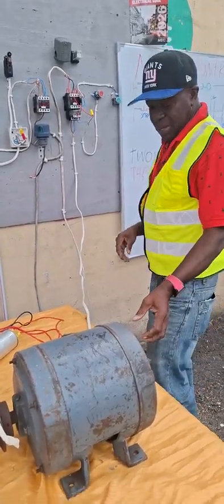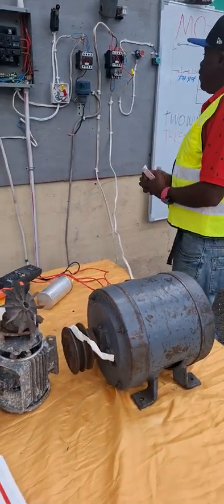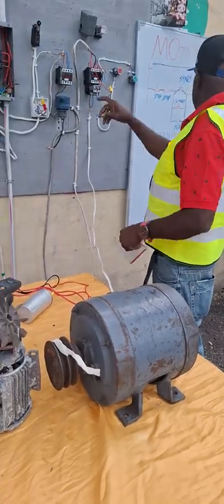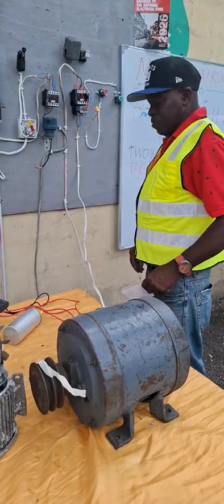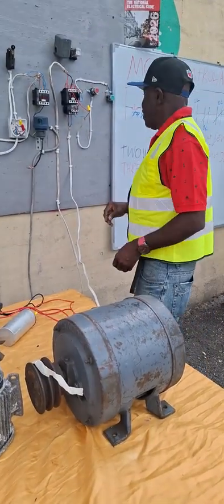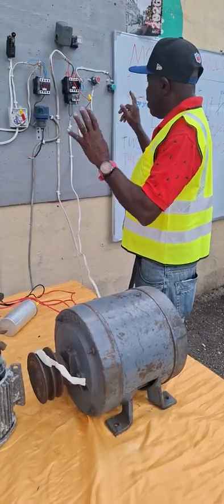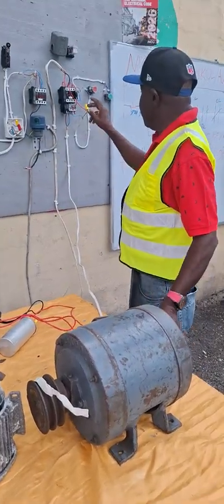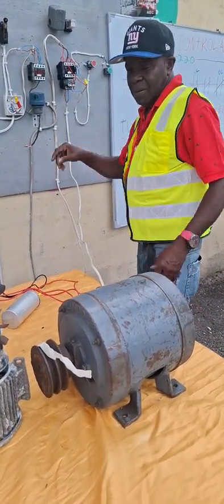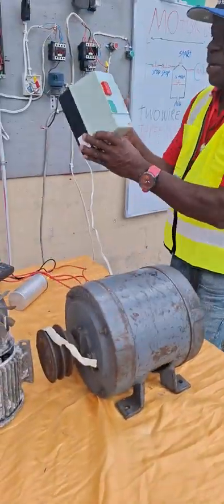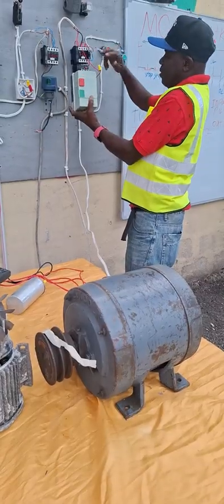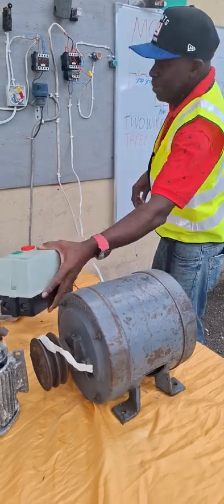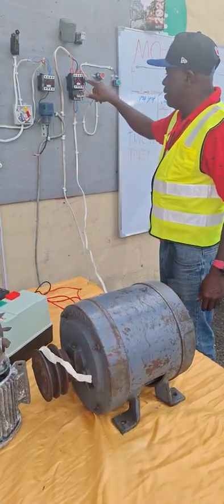Now I'm going to go to my 3-phase motor. This was a two wire control, and this is now my 3-wire control, with my 3-phase supply. I set it up so the motor can be started and stopped from two positions, right? So there's a stop and a start switch here, which would normally be the contactor. I just take out the contactor or the case here. So you have the start button and stop button, right?